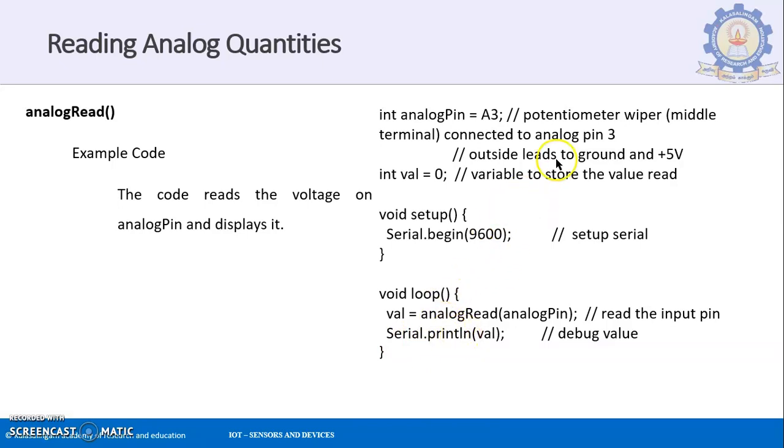If I give Serial.print, it will be executed on the same line. If, for example, the first value is 3.3 volt, then the next value of 3.4, for example, will be adjacent to it. So if I want it to be displayed one line after the other, in C programming you'll be giving backslash n. Similar case over here, you'll be giving ln. That is the difference. So Serial.println means the values will be displayed one line after the other. So with the baud rate of 9600, you will be printing the values one line after the other using the Serial.println over here.